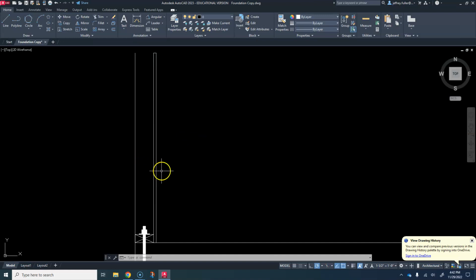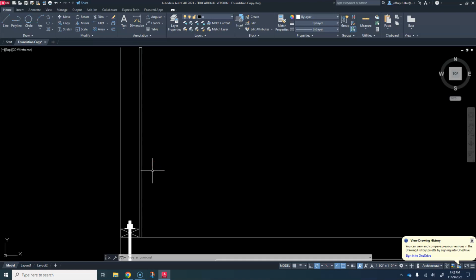Now, drywall is what we call it. We also call it sheetrock. We also call it gypsum wallboard. We call it wallboard. We call it several different things. But if you hear any of those terms, that's what they're talking about, gypsum plaster wallboard, where the material inside of it is gypsum. And then, of course, there's paper on both sides of it. The paper and the gypsum are put into a mold, and they're squished together with a type of glue, I guess, and pressure, which all makes it like a solid sheet.